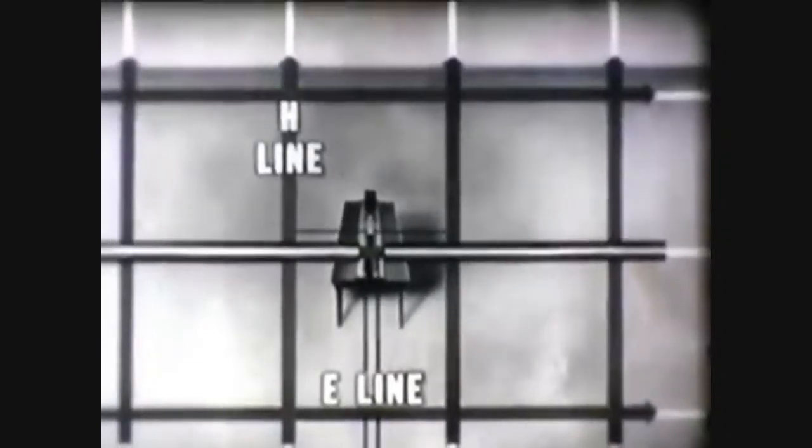For instance, stopping the wave, we see that the magnetic or H lines are still perpendicular to the voltage or E lines. Also, we see that the E lines in this wavefront remain horizontal or parallel to the Earth's surface. Because of the direction of the E lines, we say that this wavefront is horizontally polarized. In order for a signal to be received at maximum intensity from this wave, the H lines of the wavefront must cut the receiving antenna at right angles.